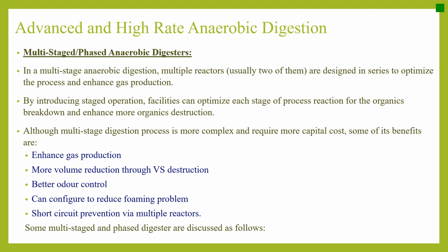Let's move to multi-staged or phased anaerobic digesters. In a multi-stage anaerobic digestion, multiple reactors, usually 2 of them, are designed in series to optimize the process and enhance gas production. By introducing staged operation, facilities can optimize each stage of process reaction for the organics breakdown and enhance organics destruction.